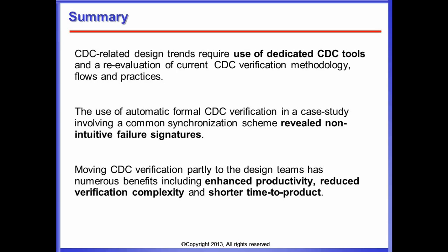Well, the real idea of it is that it allows the design team to do this verification at an earlier stage. Of course, we also have customers who are looking into the formal approach where the verification team says they see a problem, the designer says there isn't, and the verification team then uses this formal approach to prove that it doesn't work when they go back to the designer. So we have this approach, of course, as well. But it works in the front end and in the back end. It works on RTL, it works on netlist.